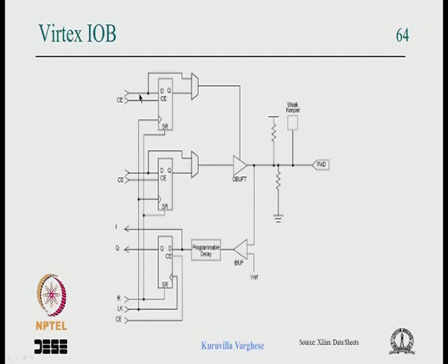And similarly, for the tri-state path, you have the combinational path or the registered path, and as we said, it can be pulled up or pulled down, because when you are tri-stating a signal, it is floating, noise can get picked up, and all the inputs can switch.